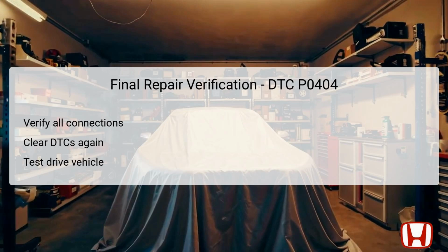After completing troubleshooting and repairs for DTC P0404, it is essential to carry out a final verification to ensure that everything is functioning correctly. Start by thoroughly checking that all connections to the EGR valve and related components are secure and free of corrosion. After verifying hardware integrity, clear any previously stored DTCs using the HDS to reset the system.